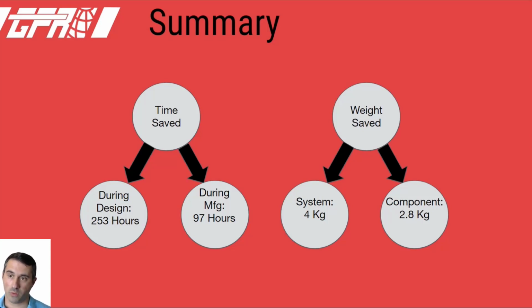It could be something simple. One that I use all the time is just one that simply hits mesh, and then once it's finished meshing, it hits the run button. So it's really simple, but it saves you from having to wait around for it to finish meshing and then manually hit the run button. It just does both back to back. So it can be as simple or complex as you want it to be. And I never had to go in and do any manual Java coding or anything. Obviously, if you had that kind of experience, it helps a lot.